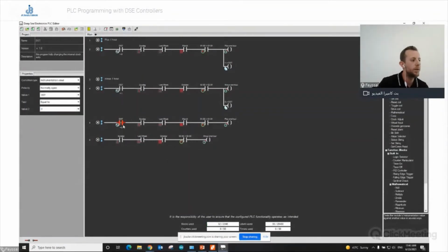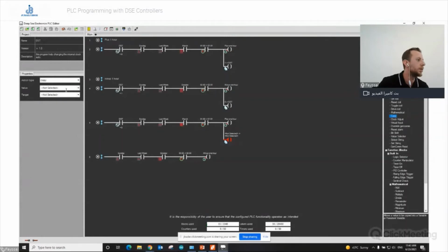Now what I want to happen, if it's 0 and we are in the specific timing of this year, I'm gonna add 1 hour to my clock and I'm gonna write 1 into this persistent variable. So I'm gonna use the copy action. So I'm gonna do this and I'm gonna choose my value. So it's a fixed value, it's equal to 1. And I'm gonna write it into my DST persistent variable. Makes sense? I hope it does.